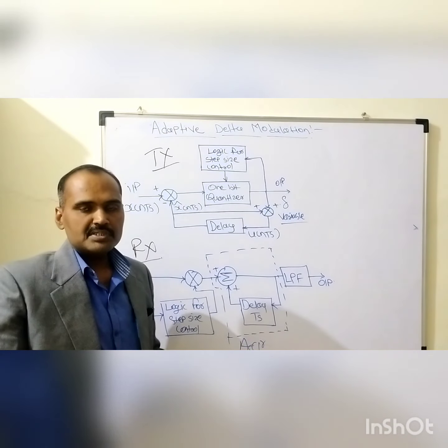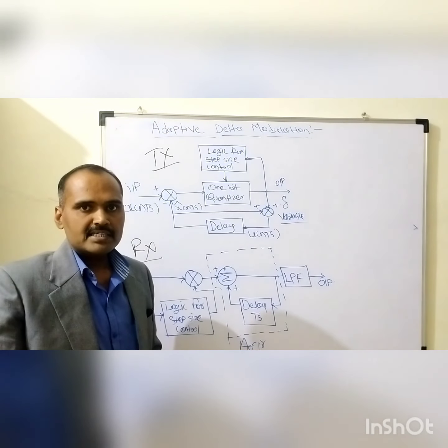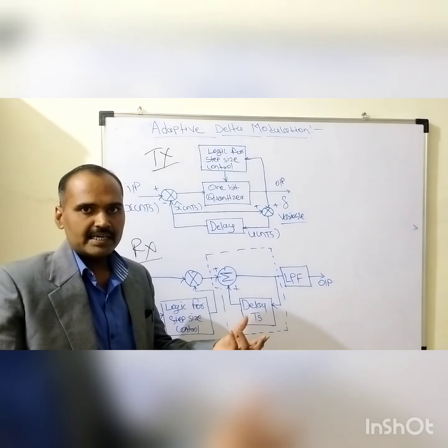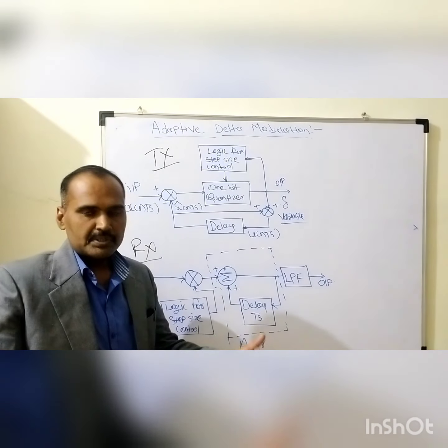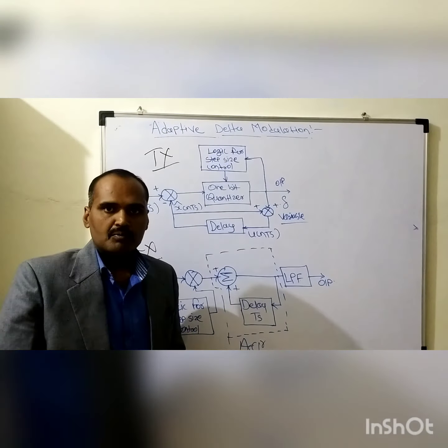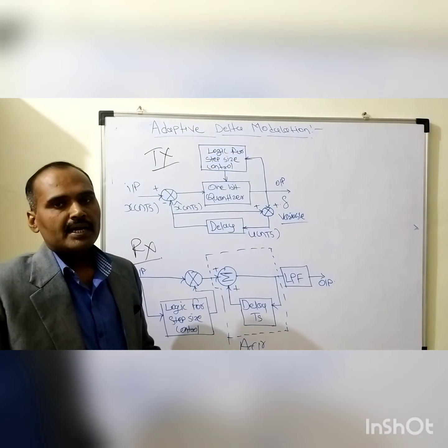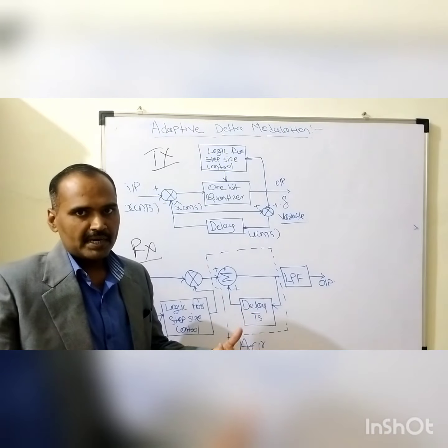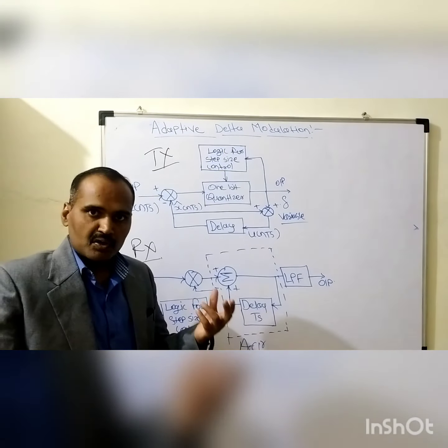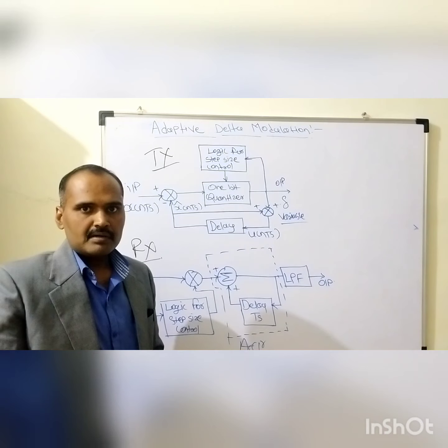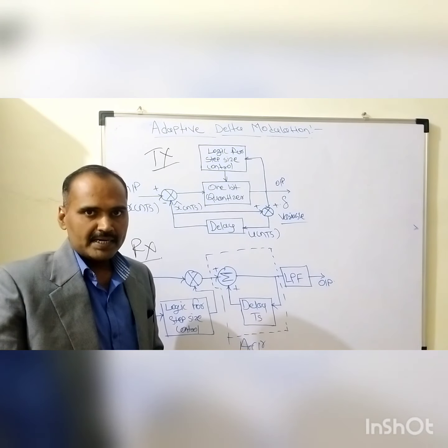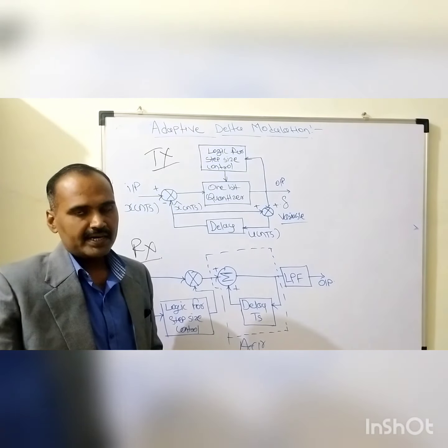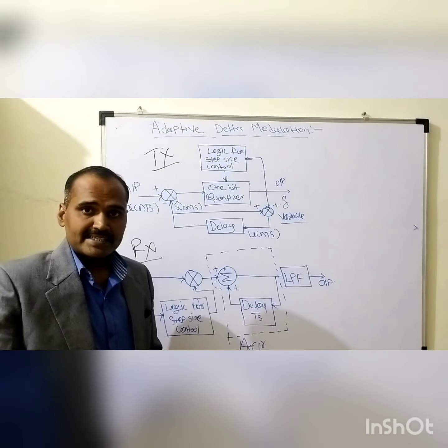Another name given to delta modulation is the one bit quantizer. In order to improve the signaling rate or effectively utilize the transmission bandwidth, the delta modulator tries to replace each and every sample with either binary 1 or binary 0. Instead of encoding each sample with a finite number of binary bits, each sample is encoded as a 1 or 0. This is the basic logic behind the delta modulator.